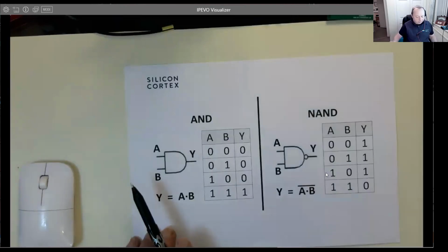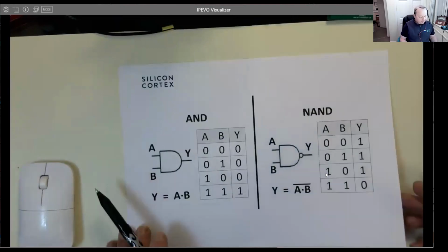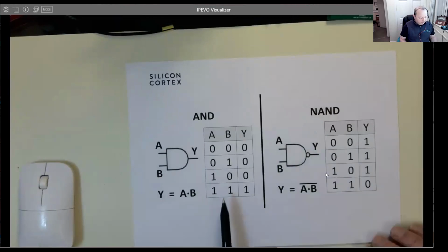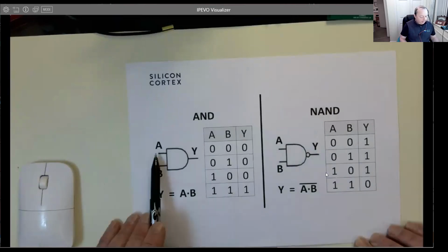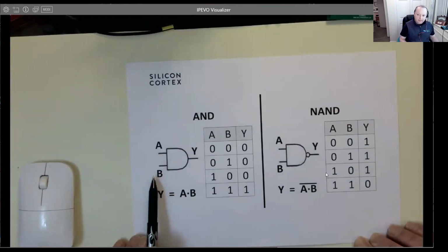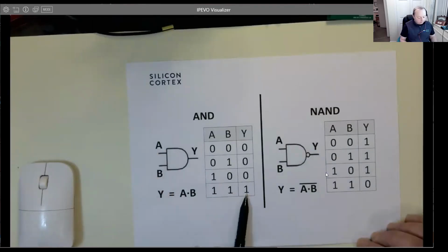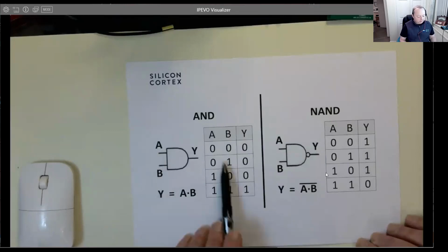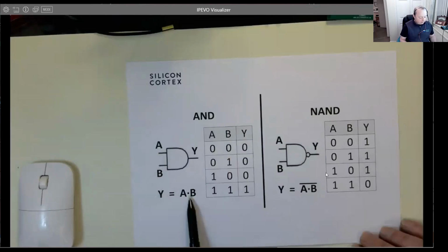The next one that we can play with is what's called an AND gate, where the output is logic high when A and B are logic high. I've written out the entire truth table. I've got two inputs, and so for the combinations of 0 and 1, there are going to be 4 of them. And for an AND gate, we tend to denote it just with a dot between the two.